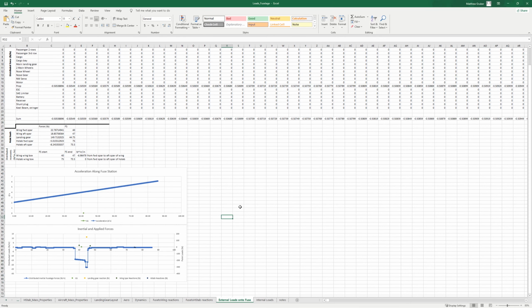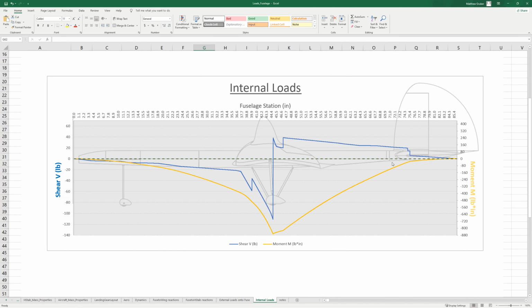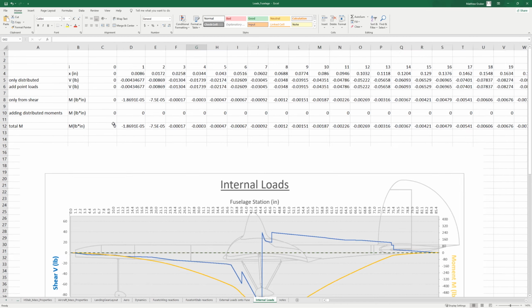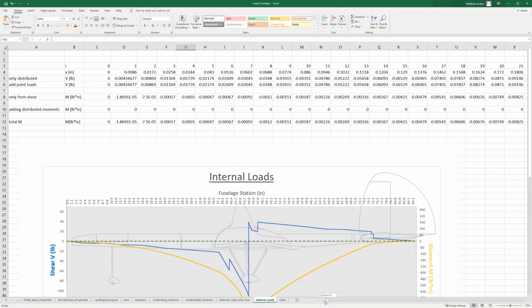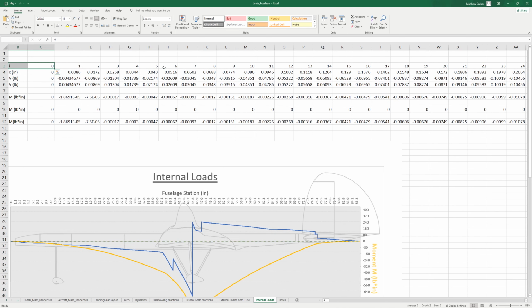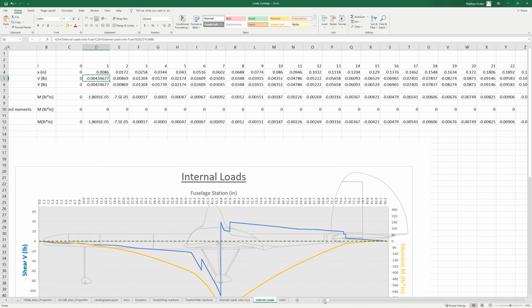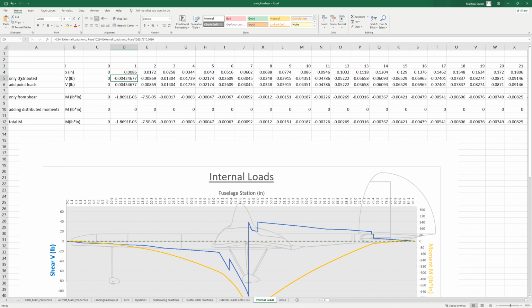So now we have all the information we need to accumulate all of these external loads and applied loads and moments to the structure overall to get this graph. What that looks like is we have the 10,000 increments and the x along that, and the shear. We're going to accumulate the shear from distributed and from point loads, and accumulate the moment as well.